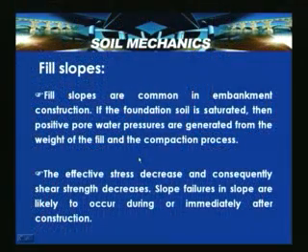And fill slopes are common in embankment construction. If the foundation soil is saturated, then positive pore water pressures are generated from the weight of the fill and the compaction process. Because of the weight of the fill and the compaction process, the positive pore water pressures are generated. So, the effective stresses decrease, and consequently the shear strength decreases. Slope failures in fill slopes are likely to occur during or immediately after construction.